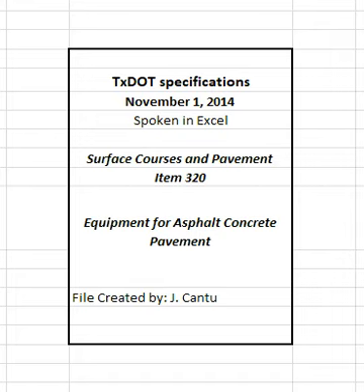2.1.2.4 Mixer. Equip mixers with an adjustable automatic timer that controls the dry and wet mixing period and locks the discharge doors for the required mixing period. Furnish a pug mill with a mixing chamber large enough to prevent spillage.